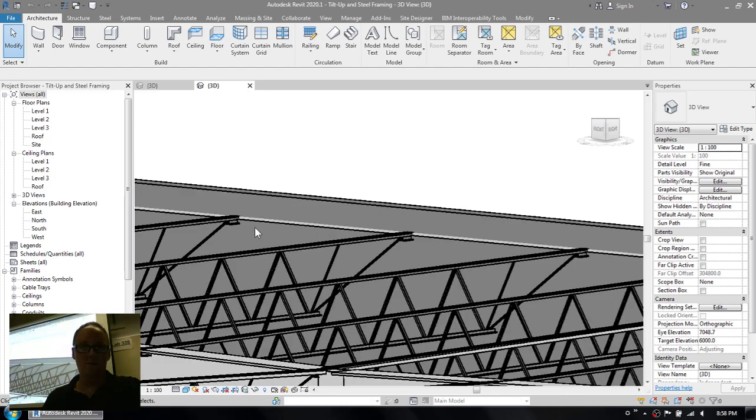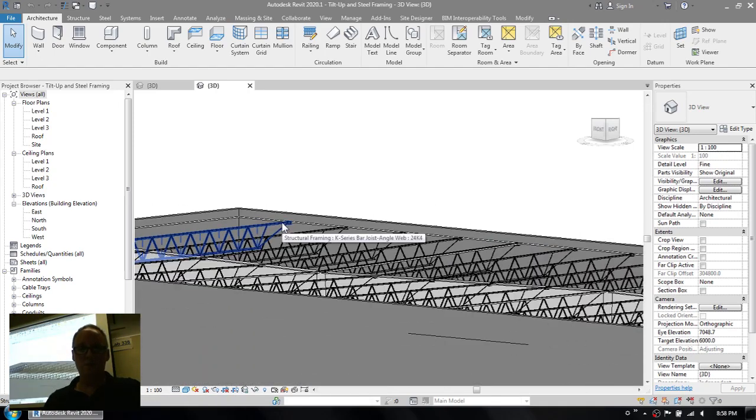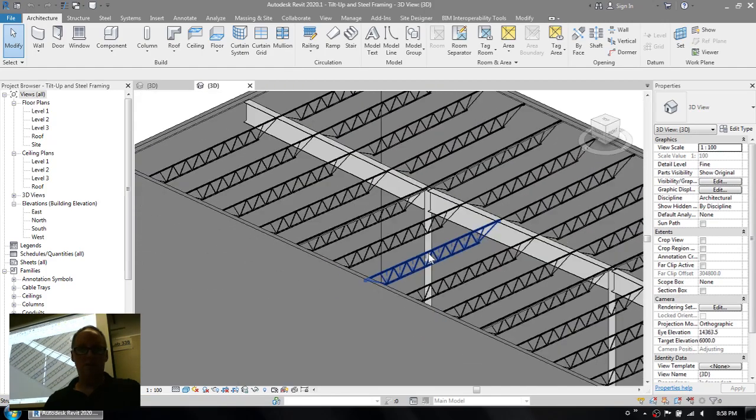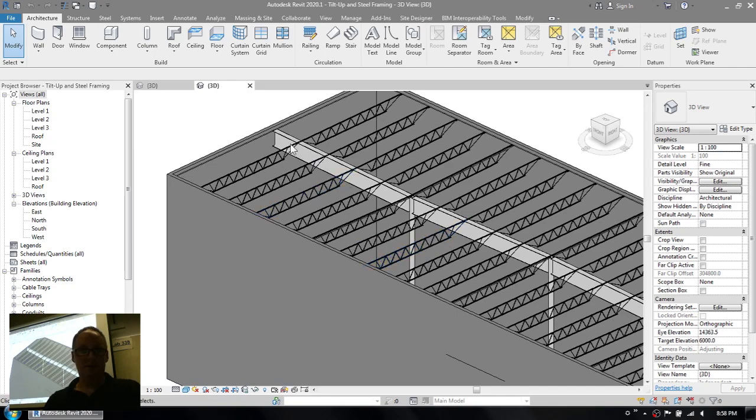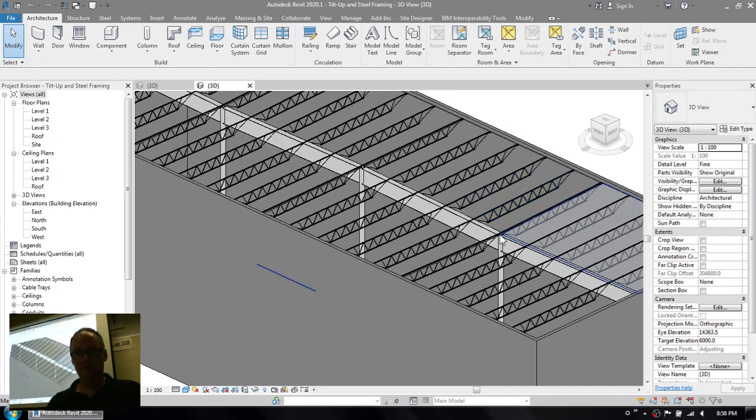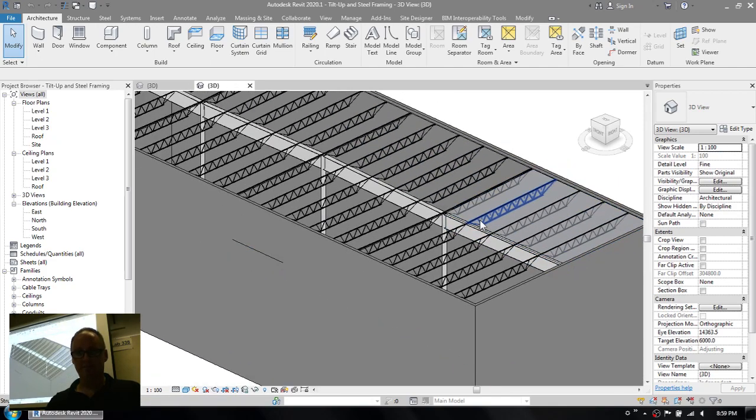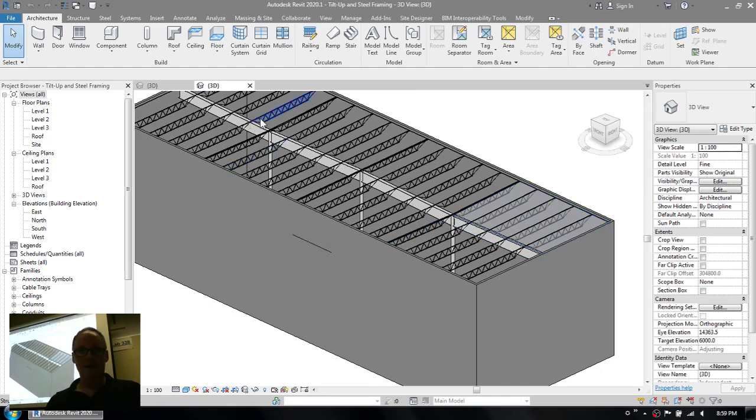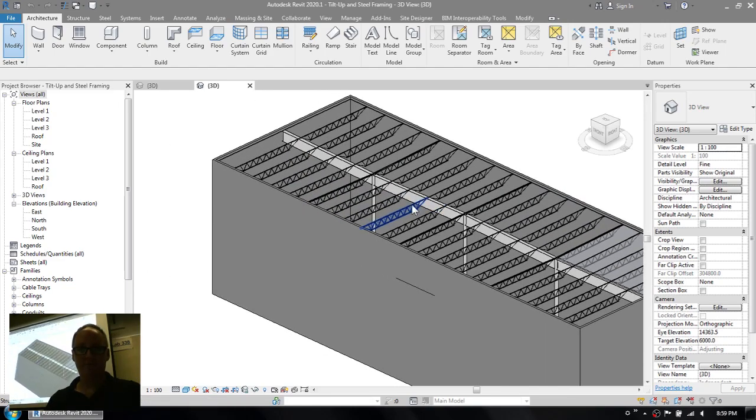Now, of course, we're not welding the pocket, but we've got all the open web steel joists at one elevation there. On the inside, we've got columns here where the structure slopes down to the column from the outside wall. Then it slopes up to the next column, and then down to the next column, and then finally up again. So there'd be a drain at the low points of the roof, and we're just going to get everything to slope into those drains.